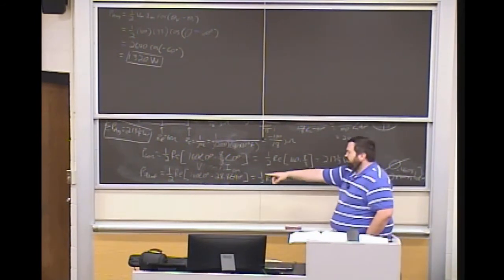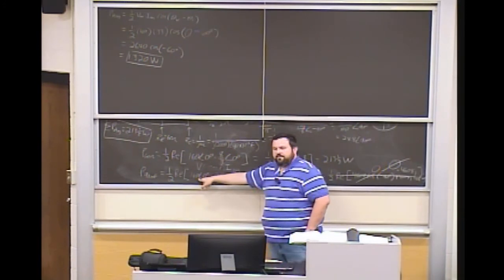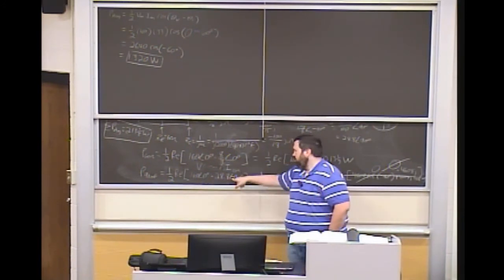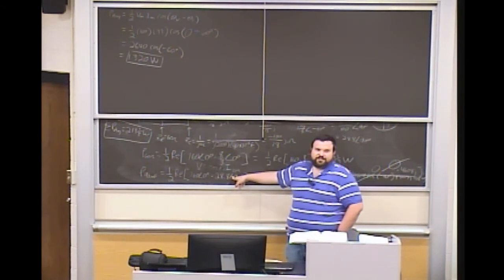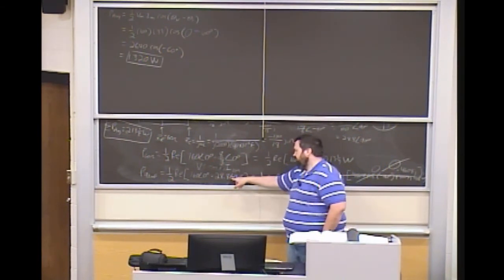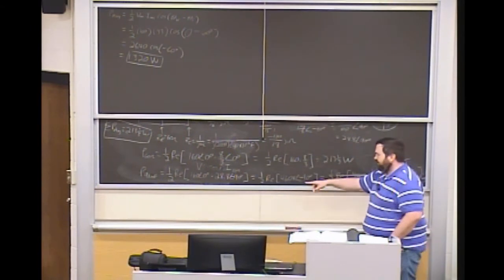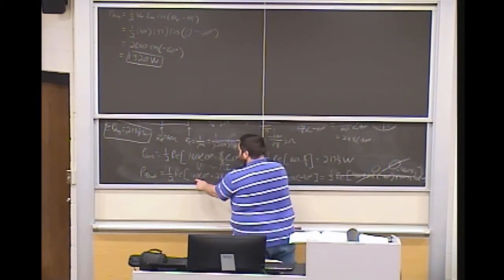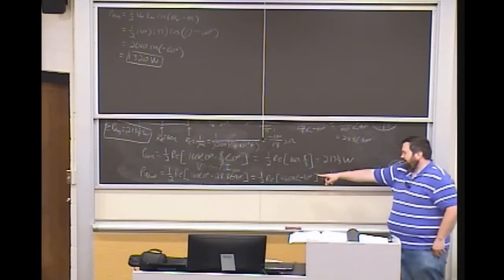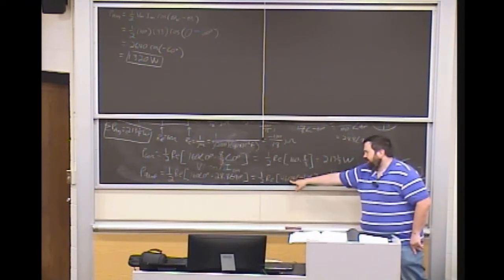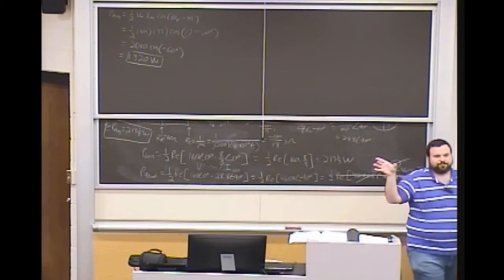So in this case, I've got my voltage phasor, and the conjugate transpose of the current, which I got just by throwing in the negative 90, or the negative sign right there. Multiplied those out: multiply the two magnitudes, add the two phases. So I get this. And then what I need to do is just get this back into complex pair.